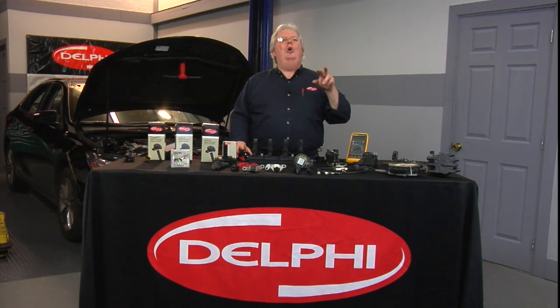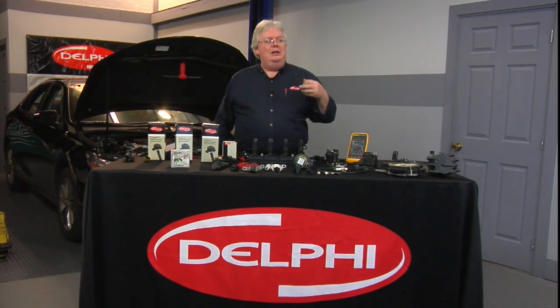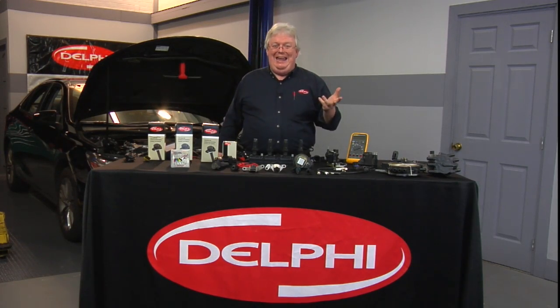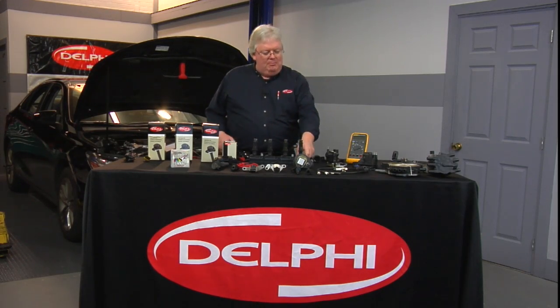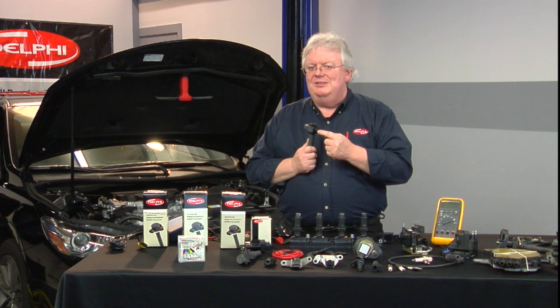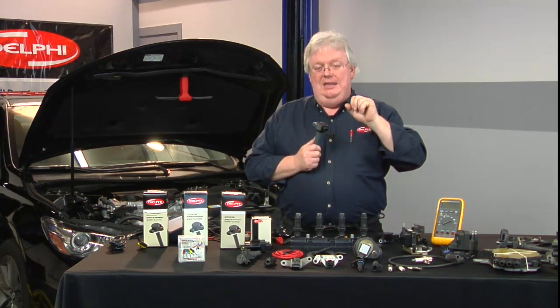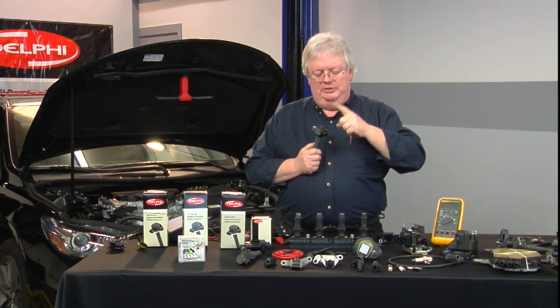Now, let's conclude on into our 4-wire smart coils for Toyota, Lexus, we'll see them on Mercedes, and a variation of 4-wire coils on General Motors. Again, there is a remote driver inside of here. So the signal we get to here is not high current as far as the pulsing trigger signal. It is a very low current signal to turn this off and on.